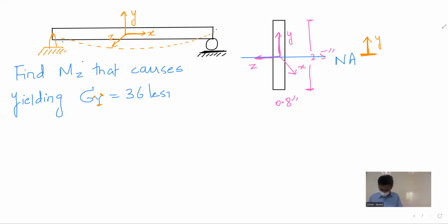So he already did it. So let me. How would you make here? For example, this will become like this, right? During bending, this means I neutral axis, that is IZ, BH cube by 12. The vertical distance is 2.5 inches, so the y will be 1.25. So it will be stress X equal to minus MZ y over IZ.